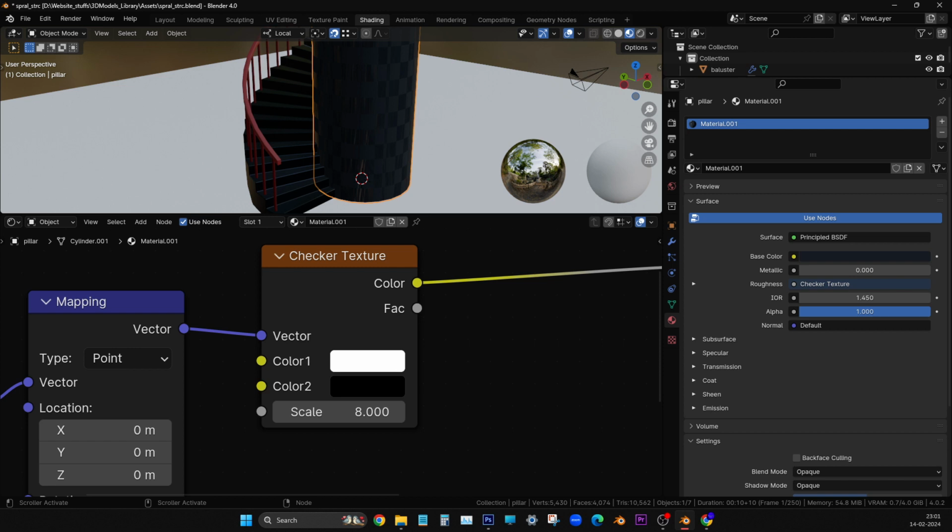Now, in the properties panel, below the outliner, is the property. Now scroll down. There you are seeing viewport display. Just open it. Now you can see passepartout, a very weird word. Passepartout. So just make it one. It is 0.5 now. Make it one. Yeah, that's right.